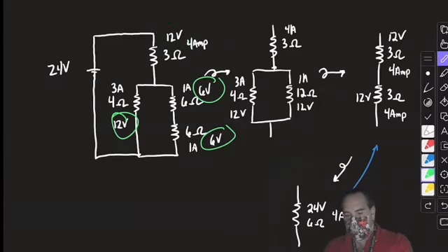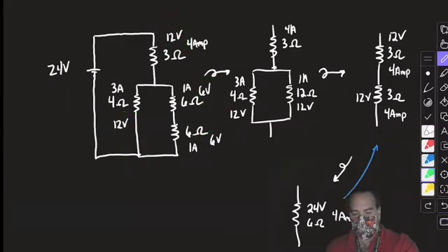However, what you could do, if you want to add something up, is compute the power at every resistor. Take a moment and compute the power at every individual resistor, please. It's not hard. Let's see. I'll do 1. 3 times 12 is 36 watts. You do the rest.